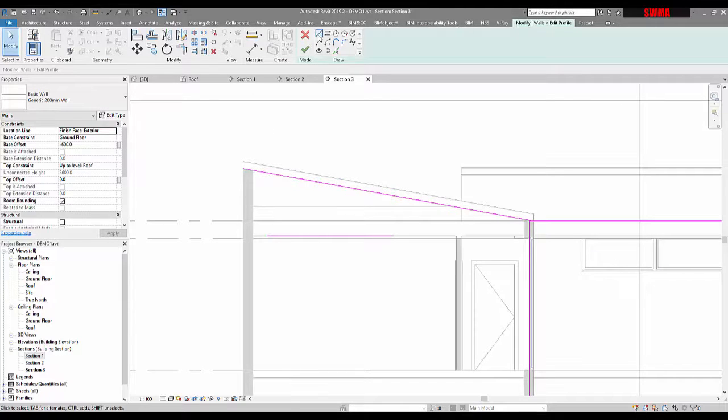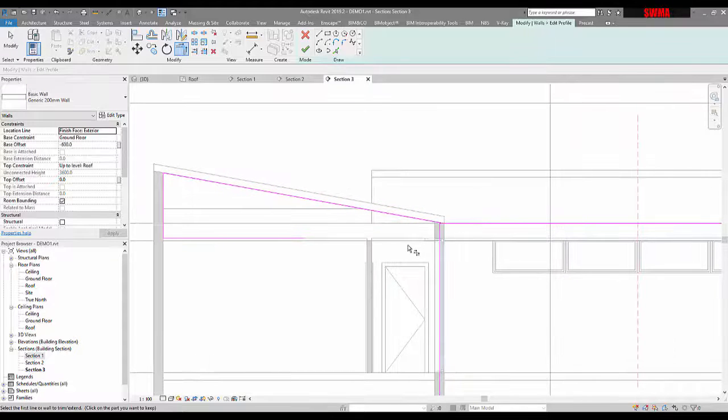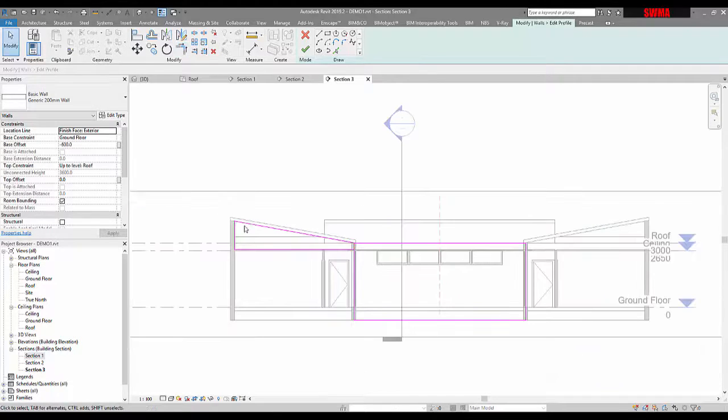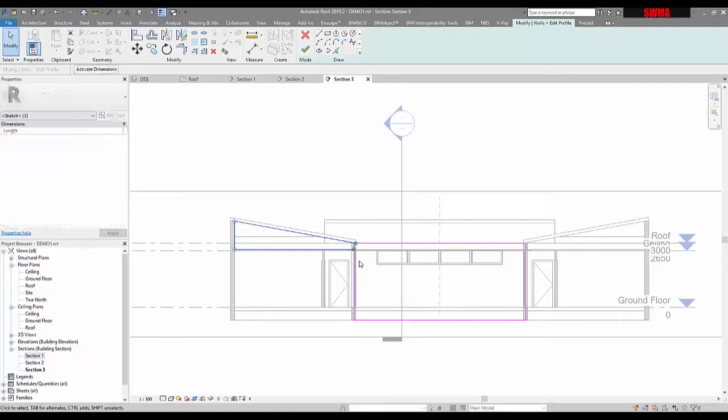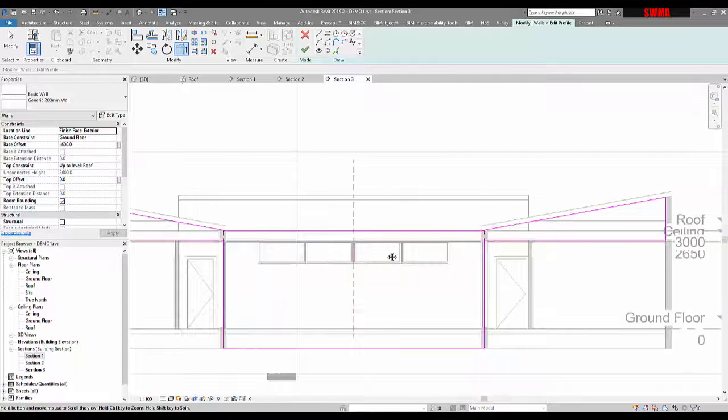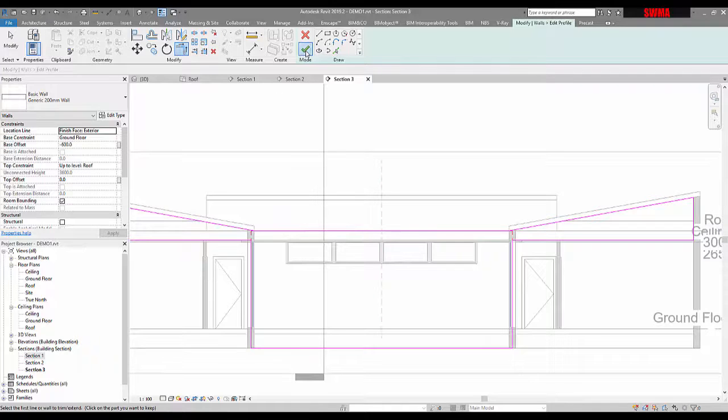Here's our modify tools, so I want to do that, and just a line here, and then I'm just going to use trim just to make sure the loops are all cleaned up. Now here I want to trim from here to here. Could do something interesting when it finishes out. And again, I always like to use the mirror command, I've got my reference plane, here it is, and then just trim that up. Okay, so let's see how this one goes.